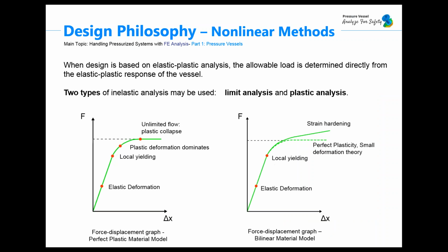And now we are starting to talk about the nonlinear methods. Basically, we can design our pressure vessels against gross plastic deformation using elastic methods and nonlinear methods. There are two types of inelastic analysis which may be used. The first one is limit analysis, and the second one is plastic analysis.